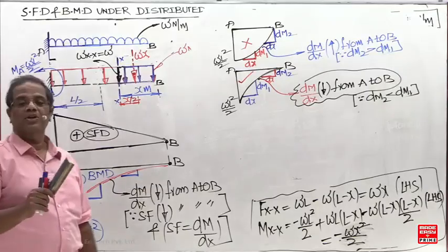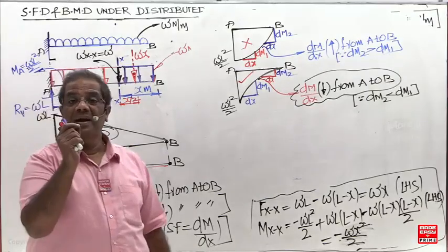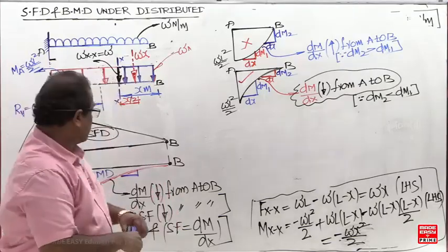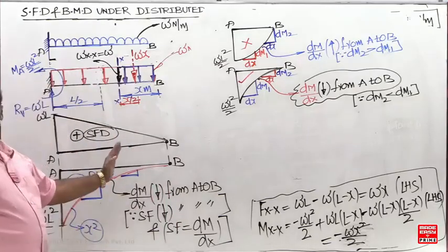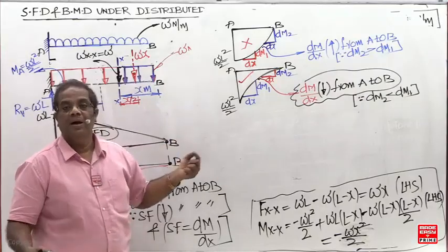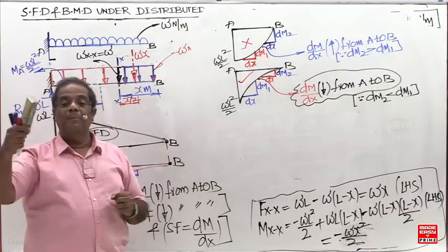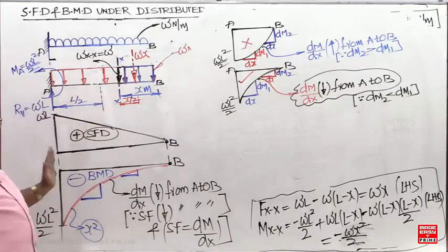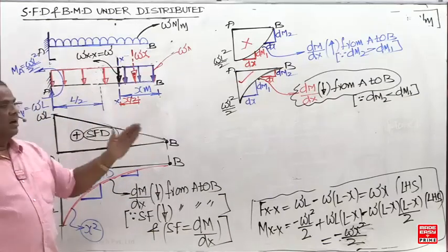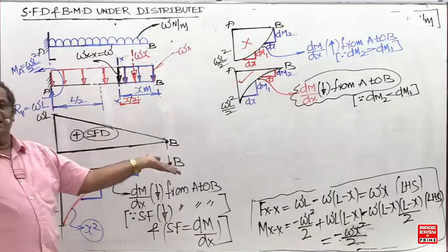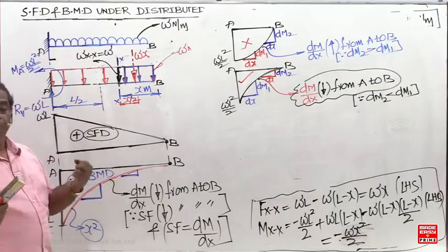So always, for the conclusion: bending moment variation is one order higher than shear force, that is already known. Here varying linearly means parabola. But you can draw two parabolas like this. So how to decide the parabola? Before drawing a parabola, first check the shear force magnitude. I want to draw a parabola from left to right. So left to right, is shear force decreasing or increasing? Decreasing. Since shear force decreases, slope should decrease.